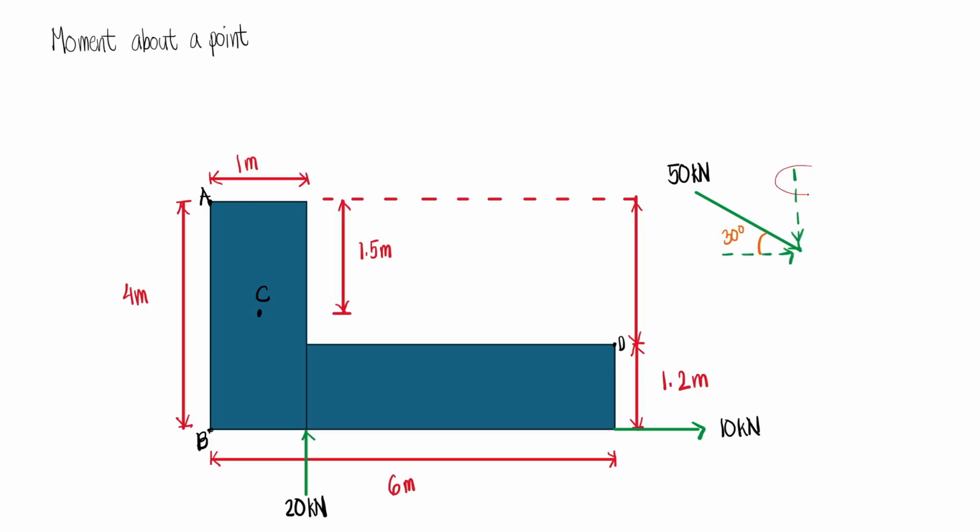Now sir, what will be this force? We can reduce this into a triangle with our inclined load as the hypotenuse. So we will form this triangle. This is 30 degrees, and our hypotenuse will be 50. We have the y component of 50, and we also have the x component. Now sir, what will be the y component of 50? To get y, we will use the sine function, because again, we have SOHCAHTOA.